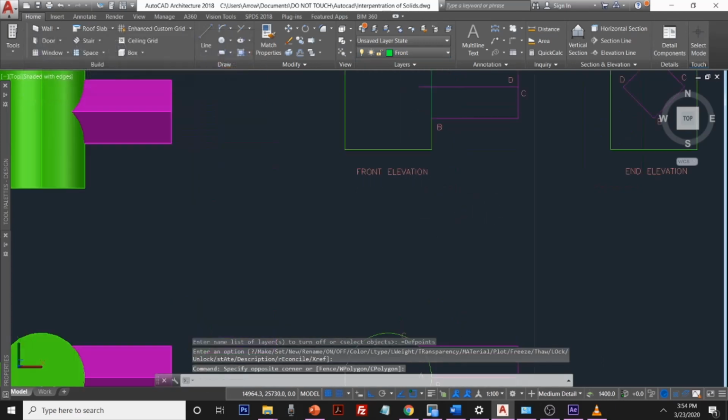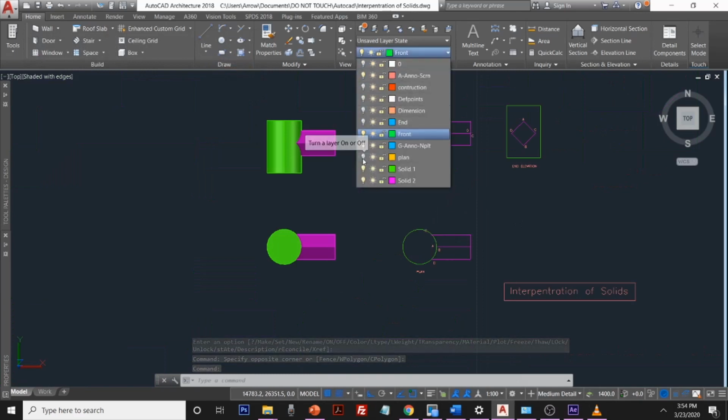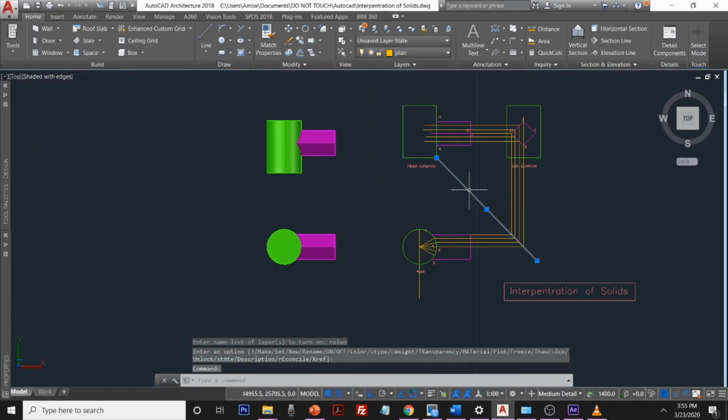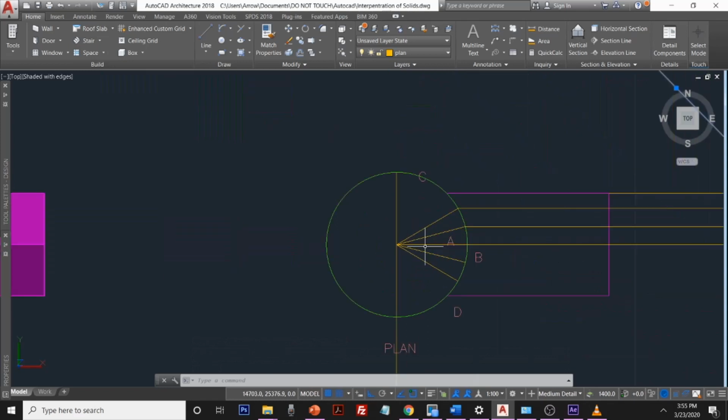Alright, so we have now our construction lines which we'll follow. Here are a bunch of lines that may seem confusing, but this is an important part of it. The 45-degree line that we had before is important. We must maintain it. And then from that now we create some radial lines. These radial lines start from the center of the circle and protrude outwards, as you are seeing demonstrated in the example. The angles at which they are projected could be 60 degree, 45 degree, and 15 degree or 30 degrees. Nevertheless, what is important is that they are equal to both sides.